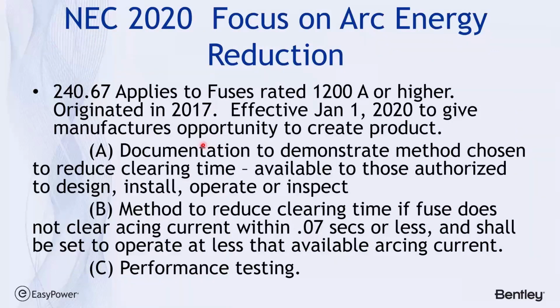Part of the change involved focus on arc flash energy reduction. 240.67 applies to fuses rated 1200 amps or higher. The requirement originated in the 2017 version, but it didn't become effective until 2020 to give manufacturers opportunity to create products to solve the issue. So documentation has to demonstrate the method chosen to reduce clearing time, and it needs to be available to those authorized to design, install, operate, or inspect.